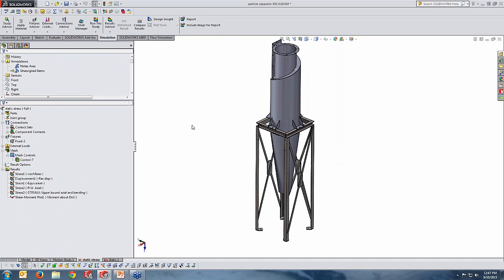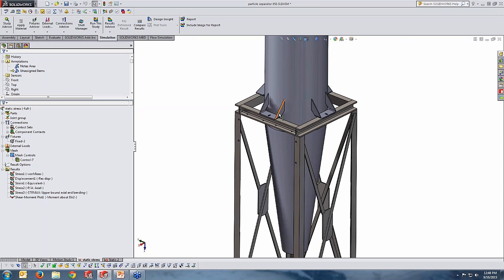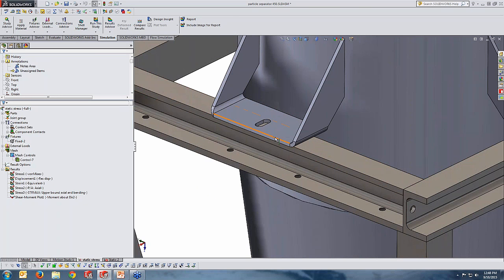Alright, based on what you may know from before, when we are talking about assemblies, there are multiple parts. And when we have multiple parts, the first thing we have to tell the software is how these multiple parts are reacting or interacting with each other. That is called contact. What we said is that since solid elements have 3 degrees of freedom and beam elements have 6, at their intersection, which might be a face or, let's say, an edge, we might create a hinge connection.